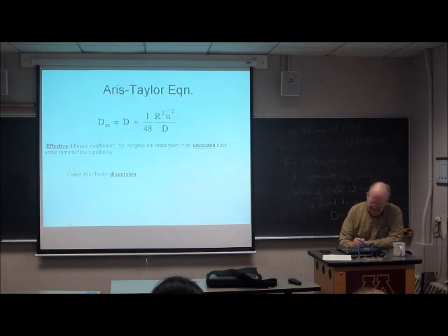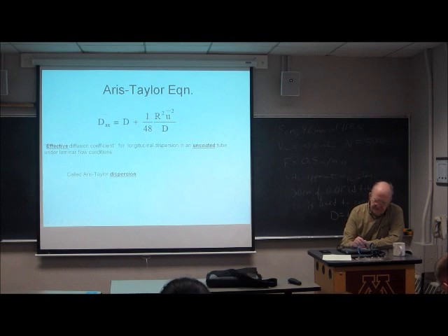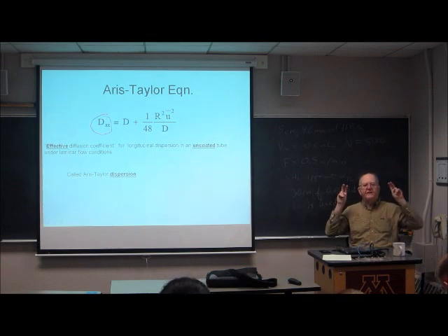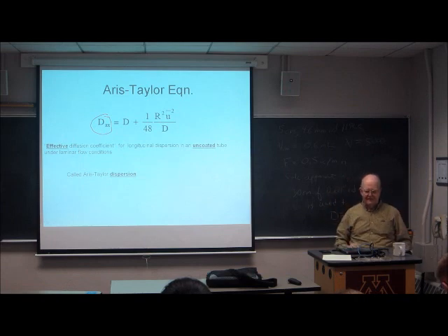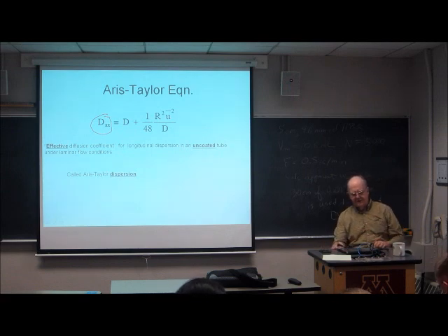Okay, so there's our friend the capillary, and there's the Taylor-Aris dispersion equation. It relates the dispersion coefficient, which is an effective diffusion coefficient for longitudinal dispersion, axial dispersion if you want, in an uncoated tube under laminar flow conditions. We're going to have to talk about laminar flow. This equation is called the Taylor-Aris dispersion equation.